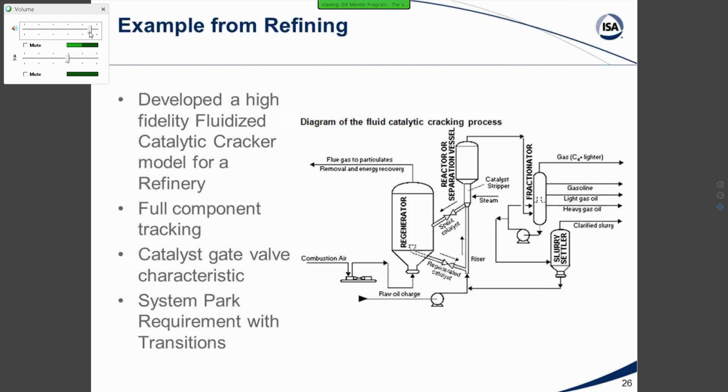Now, as soon as this becomes no longer fluidized and drops below a certain temperature, this reactor vessel essentially freezes up and the carbon just starts layering on. And actually, if they shut down the plant wrong, they have to take apart this vessel and drill out the inside, as it just filled up with carbon. So what they actually do is fill it up with this heavy oil, which is then essentially burned, and this allows the system to stay hot enough that this buildup doesn't occur. The other thing they do is that the way they pressurize the system at that point is they add steam instead of the feed.